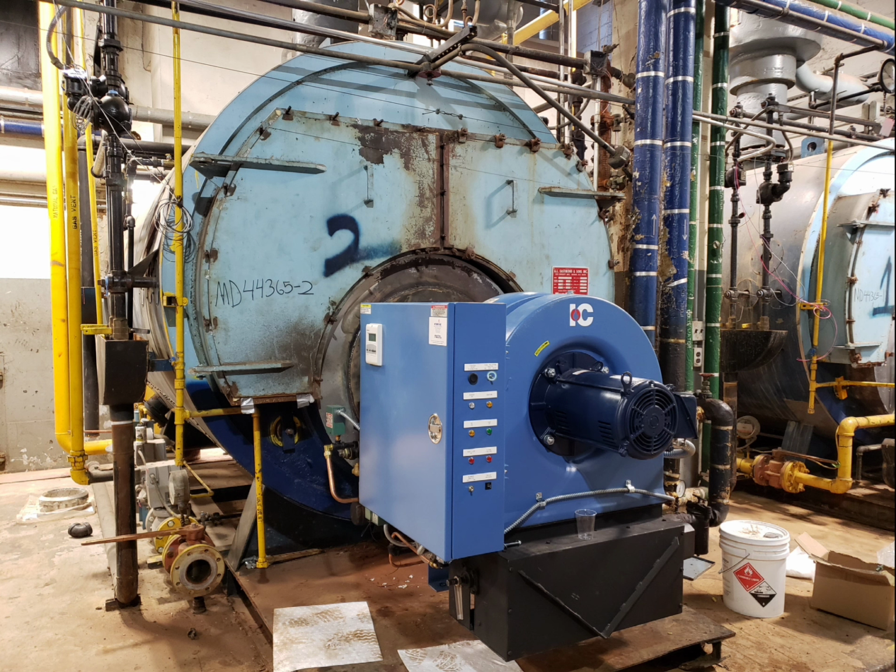The burner cycles up and it goes through its pre-purge phase. Now, the shortest you're going to get with a burner like this is a minute. You might get up to 2 minutes. So for a minute to 2 minutes straight, you have nothing but chilled air from inside of this boiler room blowing inside of your combustion chamber, cooling the tubes that are inside. And we know whenever you start to cool steam, what happens is the steam collapses, it condenses.